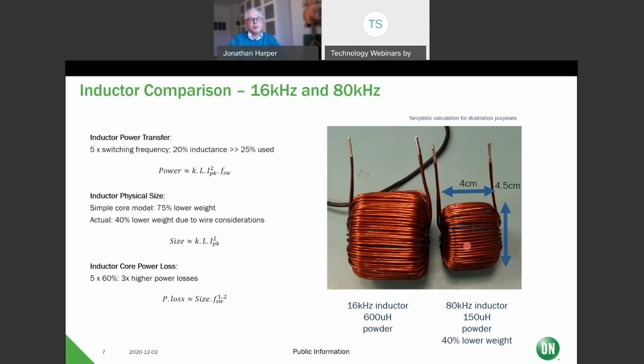I'd argue that these ones have probably got quite a high AC resistance. So this is probably biased to low core losses, high AC resistance. If you're looking at this from a formal power supply perspective, you'd be using Litz wires and ferrite cores, but that's using standard power supplies. I understand that these are the type of inductors used today in most solar inverters sold on the market. This kind of approach, but things are changing there, of course.